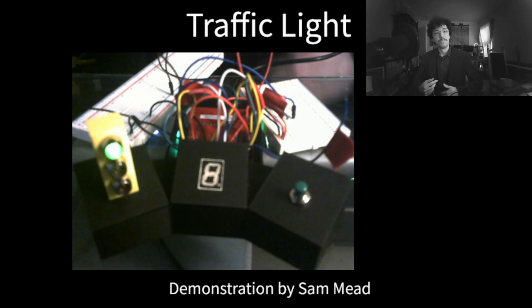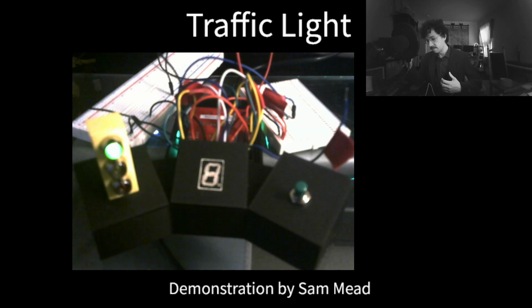So with this behavior, we are more than able to poll for input without actually using an interrupt, because we're just doing 10 milliseconds poll, 10 milliseconds poll, and all of that adds up to the full value of that light, but it's still non-blocking because we have constant periods of button checking. So we're able to poll it without creating an actual interrupt sequence.